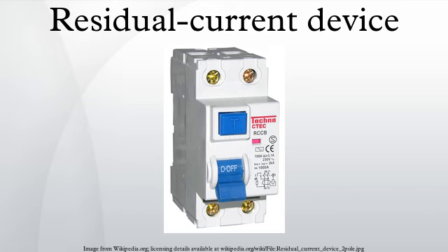Electrical hazards were of great concern in South African gold mines, and Rubin, an engineer at the company FWJ Electrical Industries, initially developed a cold cathode system in 1955 which operated at 525 V and had a tripping sensitivity of 250 milliamperes. Prior to this, core balance earth leakage protection systems operated at sensitivities of about 10 A. The cold cathode system was installed in a number of gold mines and worked reliably.